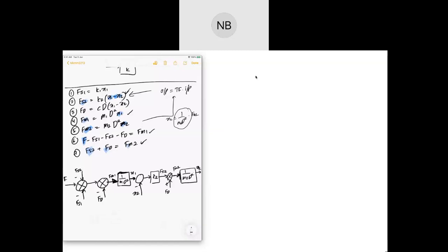All right. Now see, I already start with my force as the input to the block, and I end with x2 as the output of my block. But however, you see there are some equations not yet done. I have equation number 1 and equation number 3, the 2 equations that I have not done, so I need to complete them. Also, you see there are some arrows going to the summing point, but we don't know where they come from. We need to complete that. That is what we call the loop of your block, so you need to complete those loops.